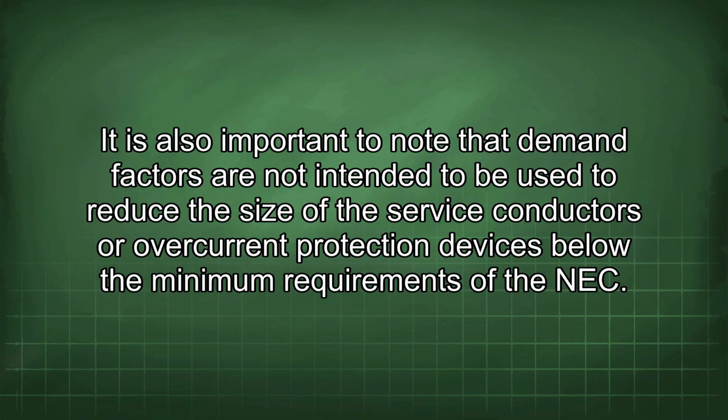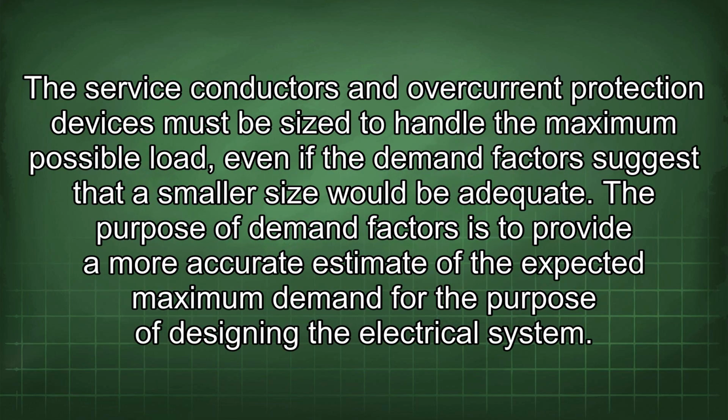It is also important to note that demand factors are not intended to be used to reduce the size of the service conductors or overcurrent protection devices below the minimum requirements of the NEC. The service conductors and overcurrent protection devices must be sized to handle the maximum possible load, even if the demand factors suggest that a smaller size would be adequate.